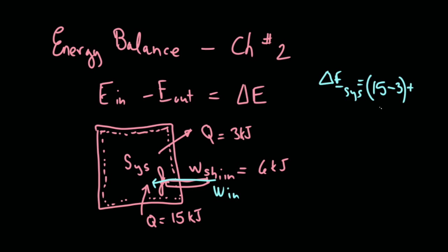and then we have another source of energy coming in, and that's work. Because if you remember from our discussion about sign convention, work going into the system is actually considered negative. And so from a previous discussion, the way we identify the first law is all the heat exchanging with the system, either into the system or out of the system, we categorize that as Q, minus all the work, whether it's going in or out of the system, we categorize that as W, so it's minus that, is equal to the change of energy of the system.